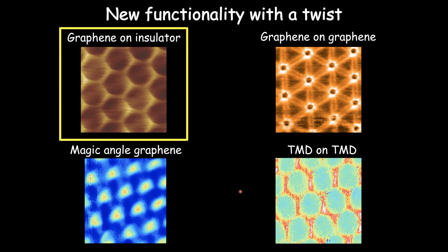All right. First one is obviously with this mechanical exfoliation, there's sort of like limiting steps. Did you find that the area size was more limited by the initial layer that you would put down in these mechanical exfoliations, or did it get progressively harder with each layer because of adherence, etc.? No, it's essentially limited by the size of the initial flakes that you can find. Some things like graphene are easy to find large flakes. Things like tungsten diselenide, the students have a much harder time finding large flakes. And that's the limiting step for that range.